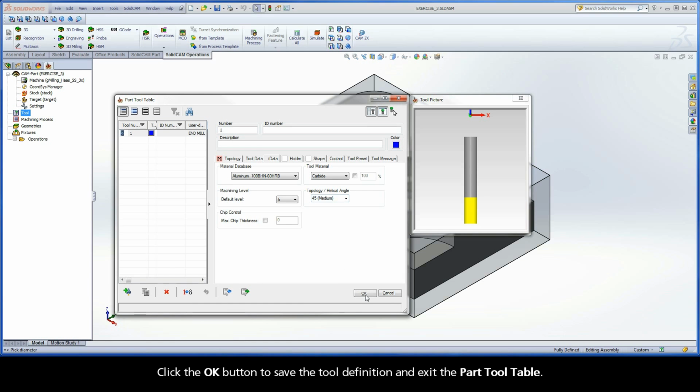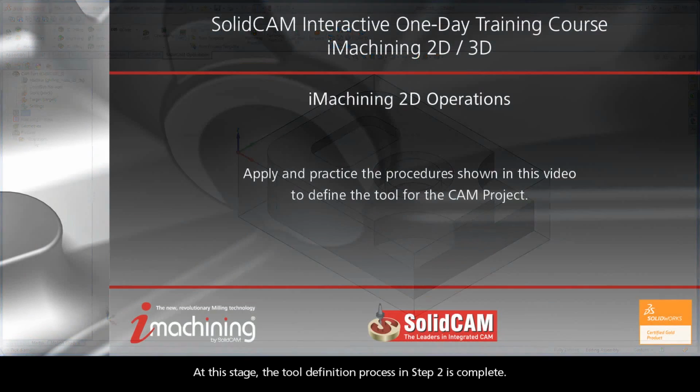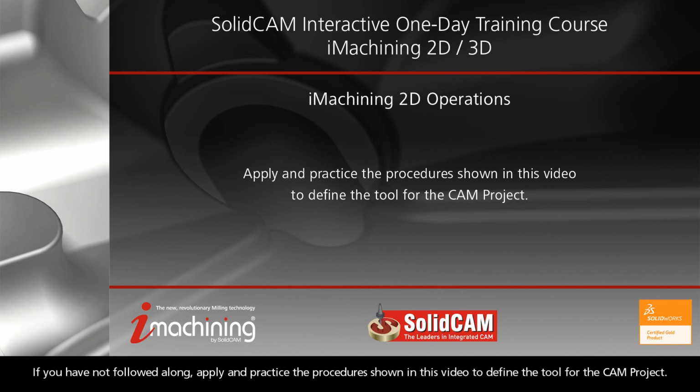Click the OK button to save the tool definition and exit the part tool table. At this stage, the tool definition process in step 2 is complete. If you have not followed along, apply and practice the procedure shown in this video to define the tool for the CAM project.